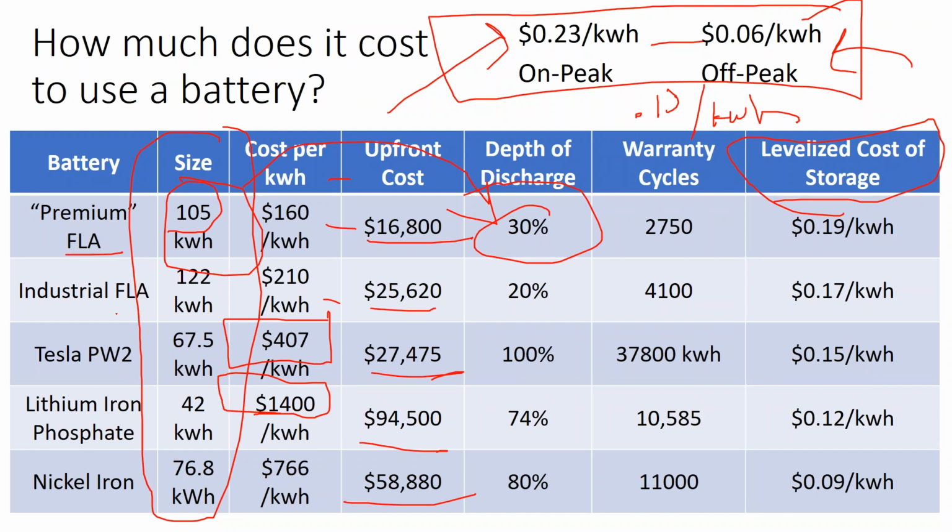So depending on what technology you use, some battery technologies can be much more deeply cycled. The Powerwall 2, you could fully discharge it down to 0 and then all the way back up. That's not quite the whole story, but that's the basic high level of it, that with lead acid, you're only supposed to be discharging to 20 or 30% on a daily regular basis. And then there are other more expensive battery technologies that you can further deep cycle. And that might mean you get away with a smaller battery, but that doesn't necessarily mean that battery is more cost effective. And we're going to talk about all of this in class. So this is just to kind of prime your thoughts.